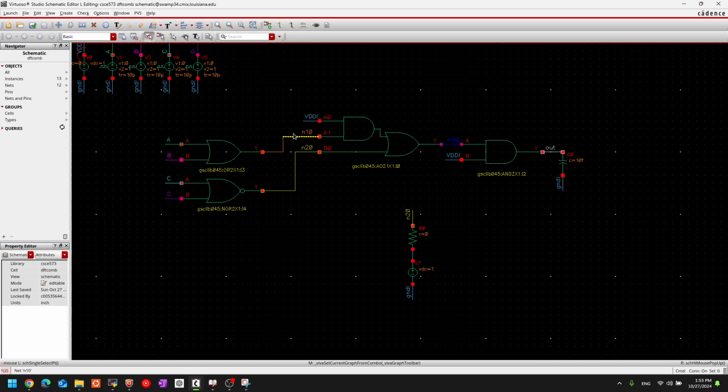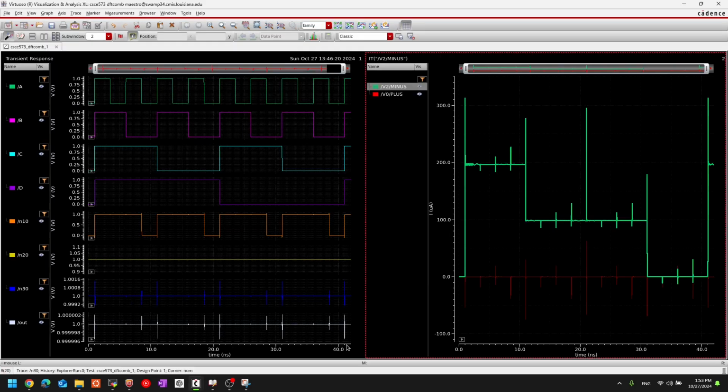And you will have a steady state current as observed here as well. So yeah, that's about it for the steady state current or for the IDDQ testing. And yeah, you could really observe the steady state currents. It's usually higher than what's expected.